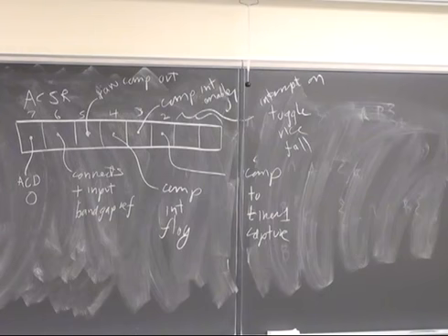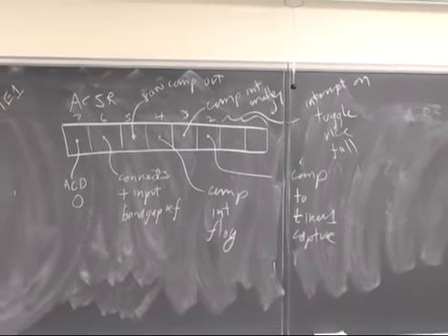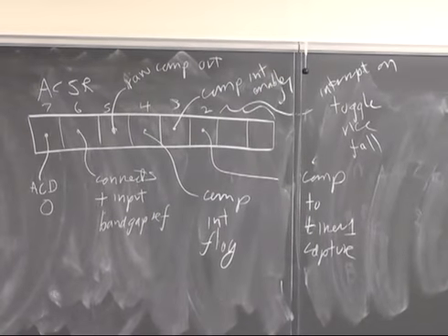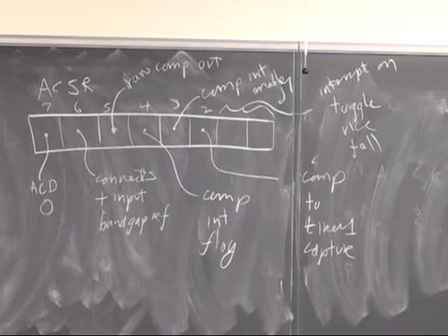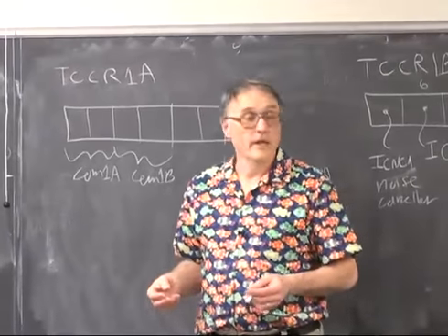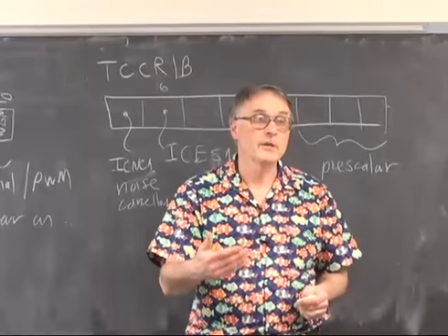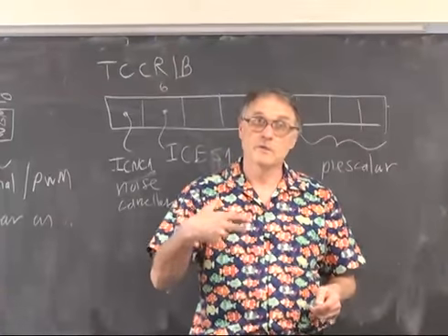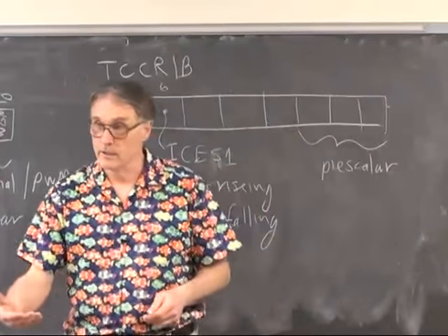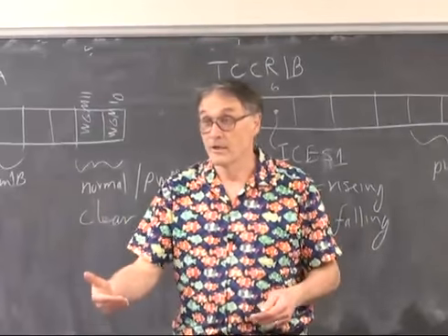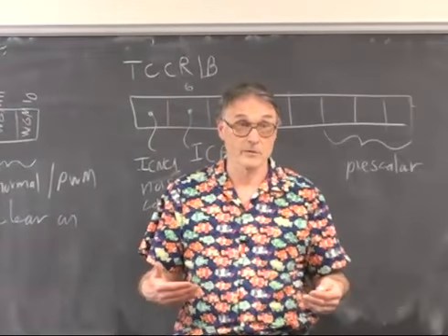So you have to set up both of these. You have to set up the timer 1 stuff. You have to set up the comparator. Once you do that, whenever you get a transition on the capture pin, actually on B.2, then you will trigger an input capture interrupt, which will store the time, which you will then read and save until the next time you get the capture interrupt.